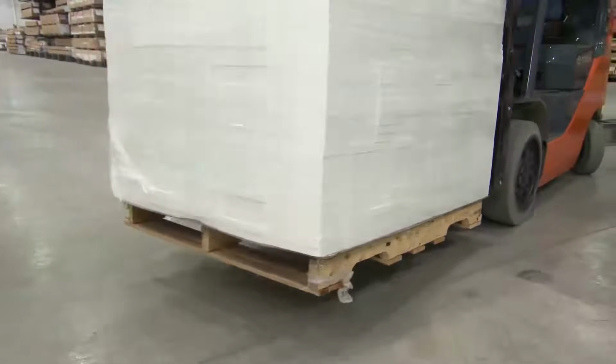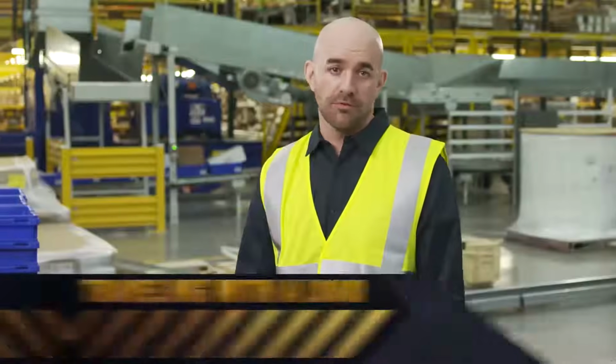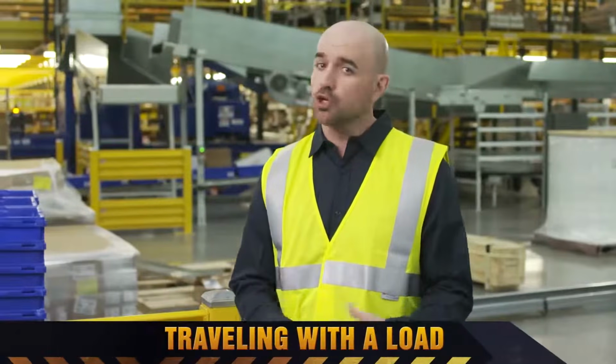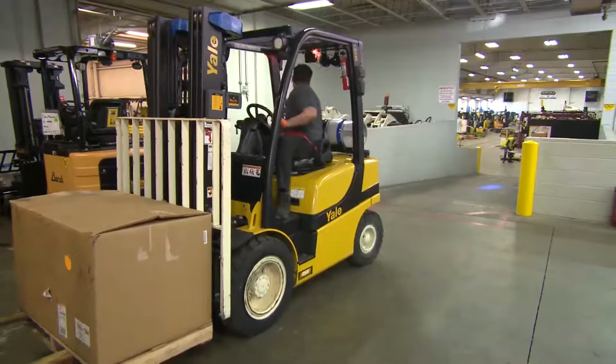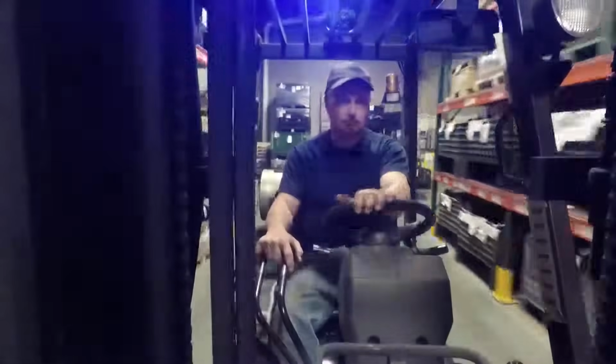Keep the forks just high enough to clear the ground, usually just a few inches off the floor if it's smooth. Before traveling with a load, make sure you know what route you're going to take. Look around you for pedestrians. Make sure your path is clear of debris or other objects. Also check to see you have plenty of clearance between your forklift and any racks or shelves. As a forklift operator, you always need to pay close attention to what's going on around you.